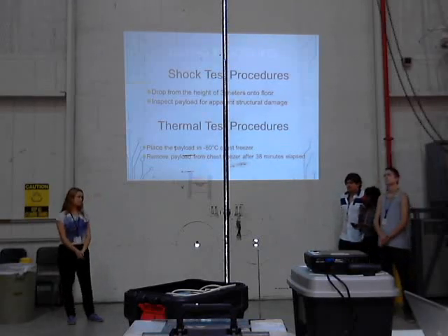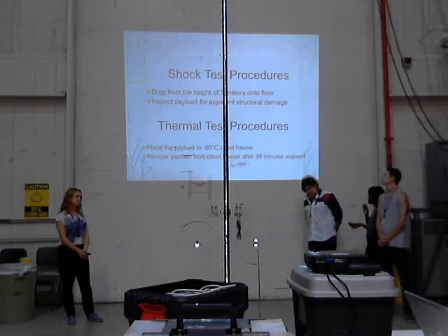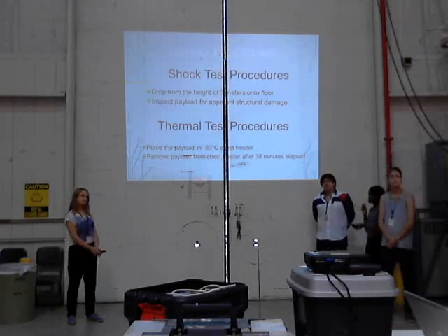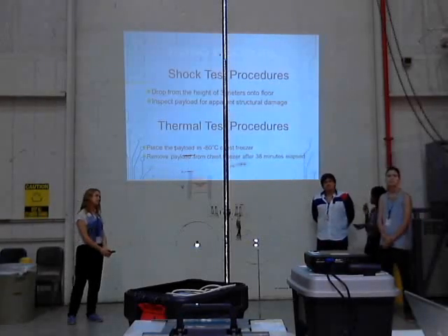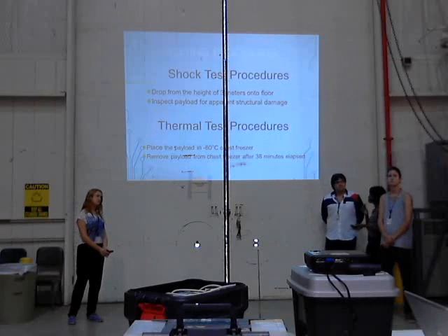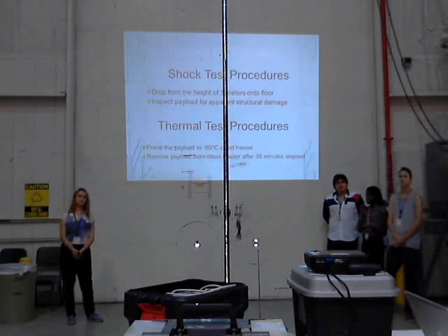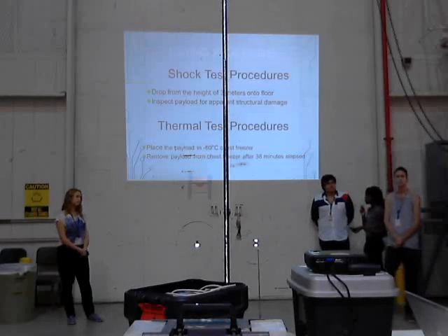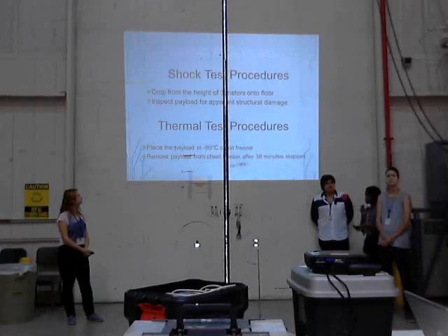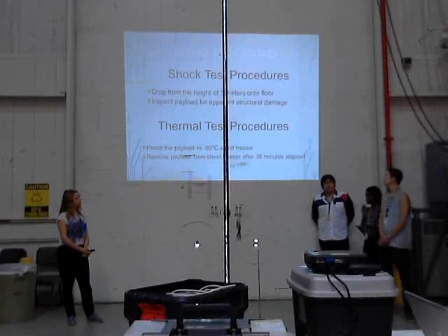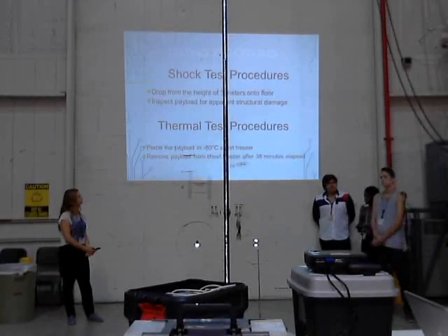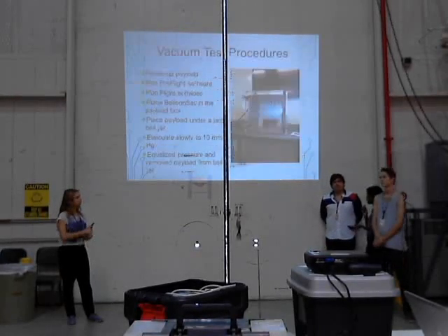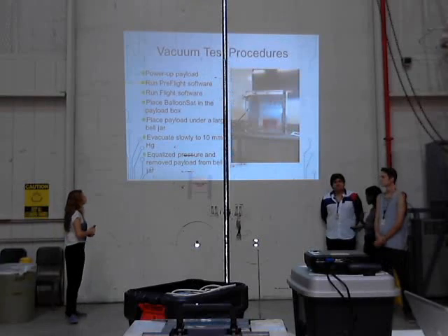So we put our payload box through a series of tests, and the first 2 tests were the shock test procedure, where we basically just dropped it from 3 meters onto the floor to see if it would take any damage. And the second one was the thermal testing, and we just put it in a negative 80 freezer and left it in there for 38 minutes to see how it would do in cold weather.